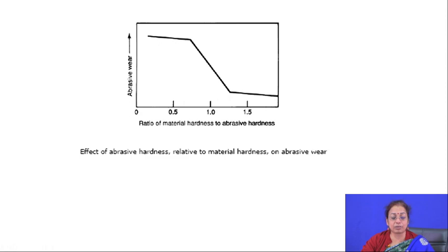Now, as I mentioned, almost all kinds of abrasive wear can be prevented if you increase the hardness of the surface. So, up to what extent should you improve the hardness of the surface? Usually, it is observed that when the component surface hardness is 1 to 1.5 times the hardness of the base metal of the mating surface, then you get the best result. Otherwise, if the hardness difference is large, naturally the wear occurs in the mating surface. So, when you increase the hardness of the component to reduce abrasive wear, you have to keep the hardness to a value of 1 to 1.25 times that of the mating surface, so that you minimize the wear rate to a large extent and there is no wear of the mating surface.